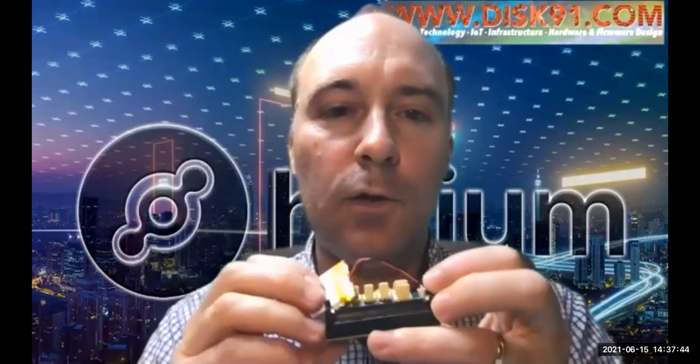So you get a board like this one, you just make some Arduino code. It can go low power, with really, really low power consumption. With a battery there, you can have about 1 or 2 years of autonomy with the system communicating every 15 or 30 minutes. And whatever protocol you want to talk with.